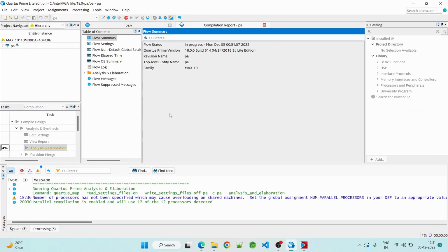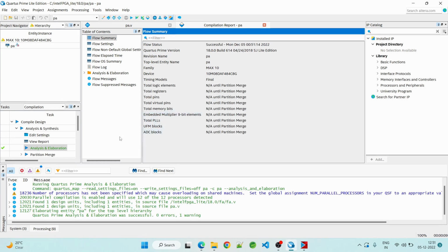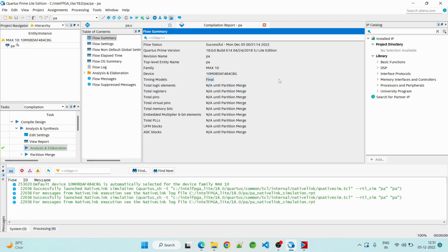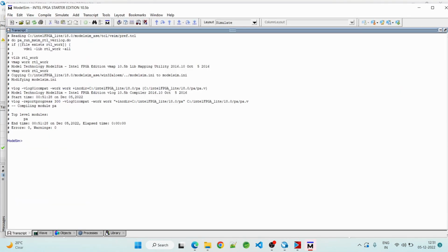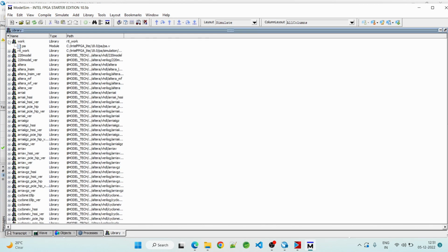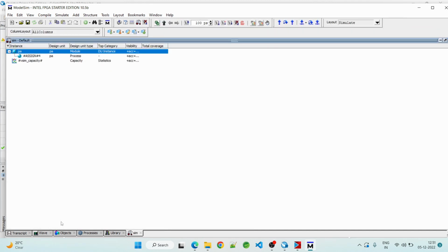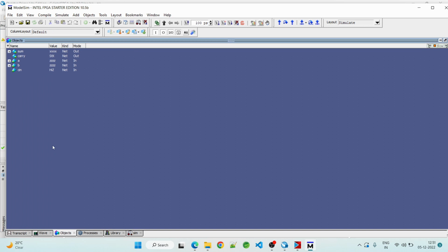So as we run the elaboration, we will get to know whether it is throwing any error or not. So it is not throwing any error. Then that means all the signals are correct. So we'll go for RTL simulation. In RTL simulation, we are just going to check the functionality. So now here expanding the work, we'll get the parallel adder. So then we'll simulate it. So then we get objects. So in objects, we get only the necessary signals.